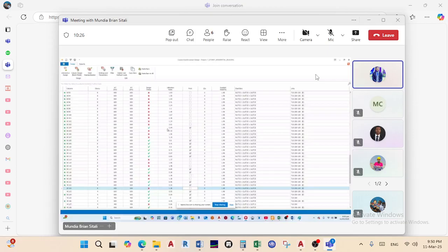I think the only thing I can reference is we have to change the cross section using the side where we came from. If we go step by step with this, we may chew into our time. So what I'll do is I'll go to beam design. Already we know if we're able to change the cross section and some of these pass, then we may need to change the section again.